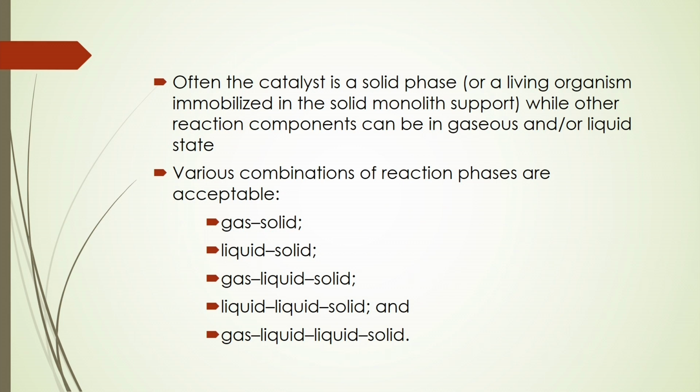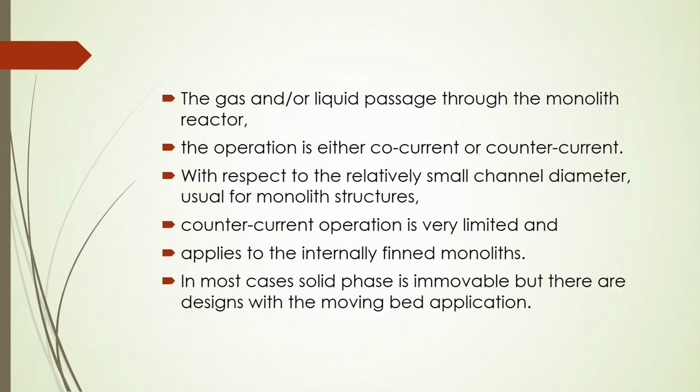Even gas-liquid-liquid-solids, sometimes liquid-liquid extraction in gas-induced operations, where you can get mixing phenomena, and even intense mixing may result in more yield of the extraction processes. And there are several other operations in the presence of monolithic structures based on this combination of gas-liquid-solid reactions. So, you have to supply those gas and liquid through that monolithic reactor. In that case, it may be co-current, it may be counter-current operations.